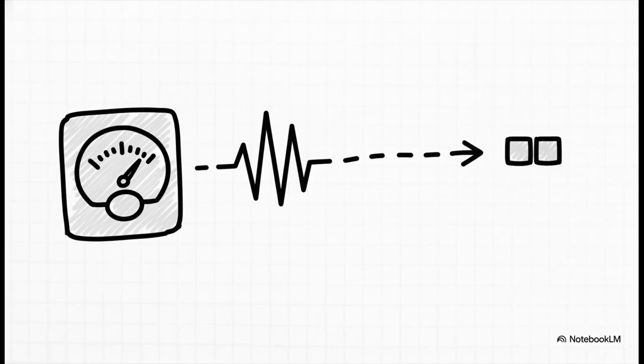Now, energy meters often have data scattered all across different address ranges. So following the exact same procedure, we'd also quickly add a second register group just to capture frequency data. According to the sample datasheet, this one sits at a starting address of 3110, and since it's just one single piece of 32-bit floating point data, our length here is exactly 2.